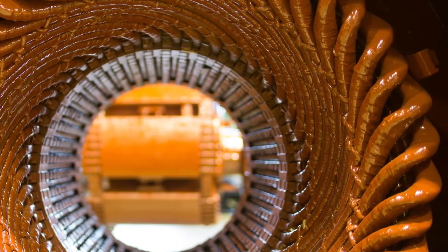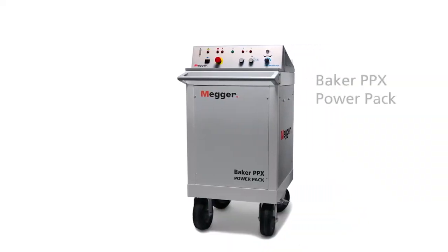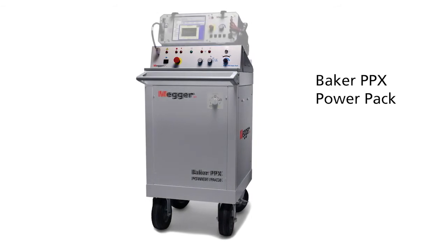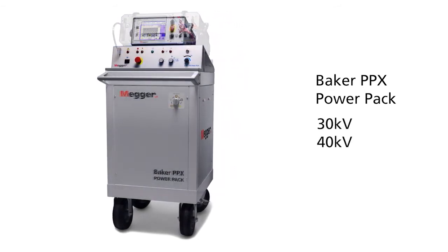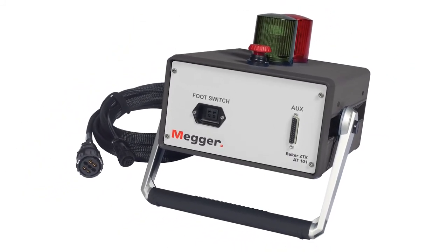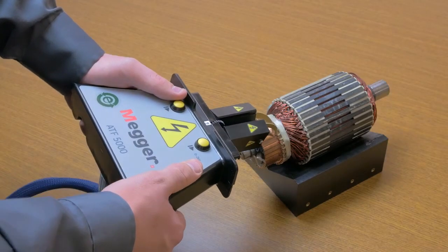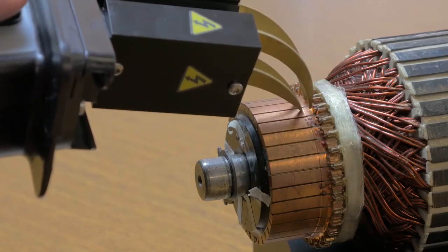For testing of very large motors or form-wound coils, the voltage range of the Megger static motor analyzers can be extended using a power pack. These solutions boost the output voltage to 30 kV or 40 kV for the ground wall insulation DC tests and the turn-to-turn insulation surge test. DC motor armatures can also be tested using the Megger ZTX adapter with a Megger static motor analyzer. The ZTX lowers the surge voltage while increasing the current. This allows bar-to-bar testing of the armature with excellent fault location.